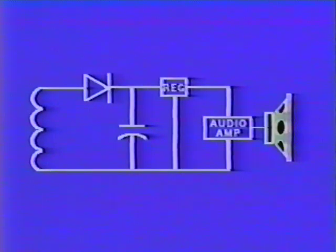Notice that the ripple grows to become almost half the peak output voltage, and that the large ripple is now discernible in the audio. Clearly, the filter needs help in maintaining a constant output voltage. The final section of a power supply, the regulator, provides a constant output voltage over a range of load conditions.